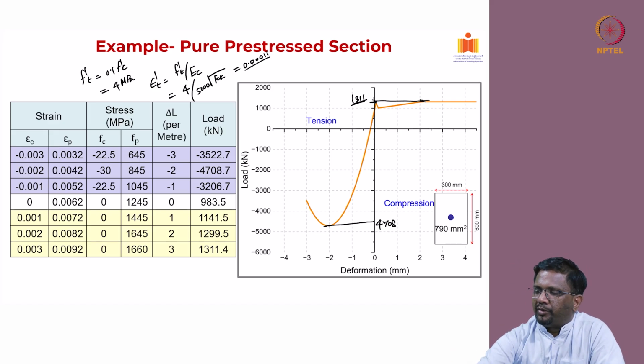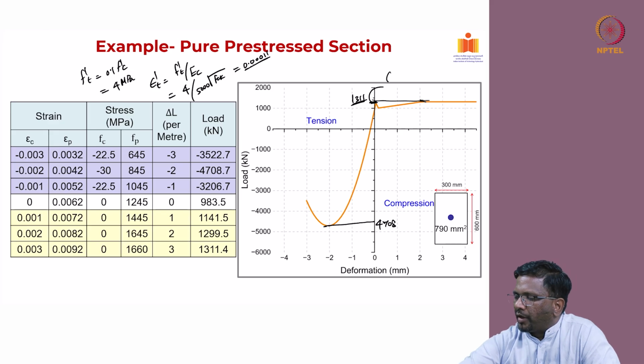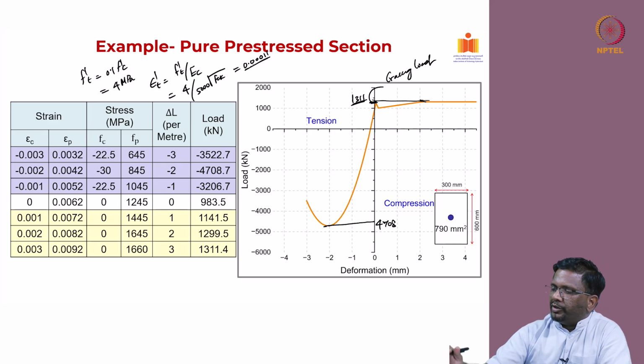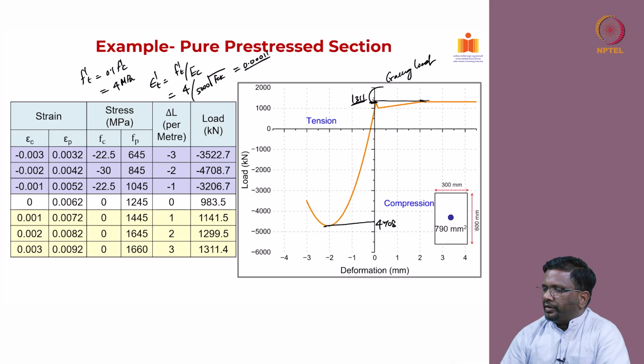So, corresponding to this tensile strain, if you do the calculations, I can get my cracking load, right. I can get my cracking load. Okay. So, you can do that. So, compared to the reinforced concrete case, if you see, the cracking load in a pre-stress system will be much higher. Okay. That we can show from your calculation. So, this will be basically when the strain is also 0, it will be slightly higher than this. Okay. So, it will be in between.